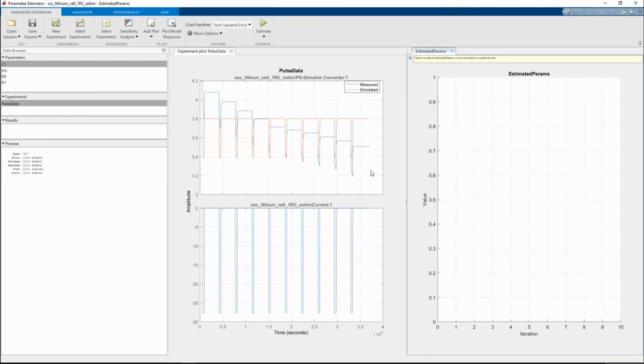When we start the estimation, Simulink runs the model over and over again, and every few runs evaluates how far it is from its objective, the experimental curve. While it is not close enough, it imposes perturbations to the values of the parameters to be estimated and evaluates if the change improves the situation or not.